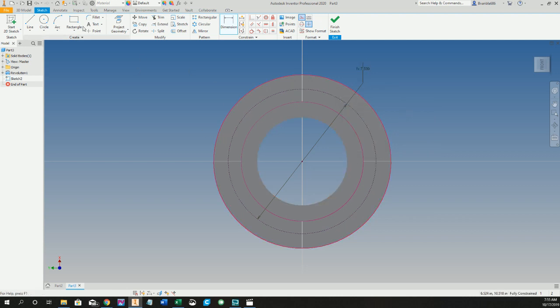And I'm going to come up here, select circle, deselect the construction, pick on the very top quadrant or the apex of that circle, drag it out and pick, hit D for dimension, pull that off, go to list parameters and go bolt hole diameter.